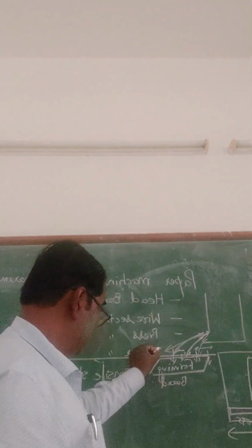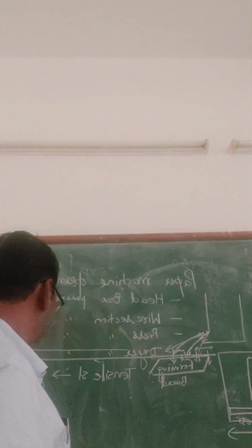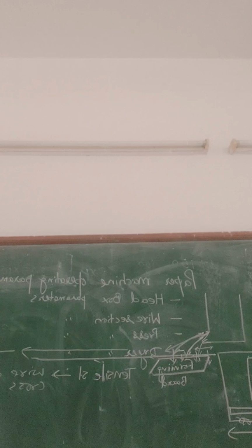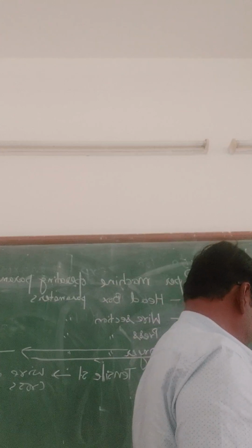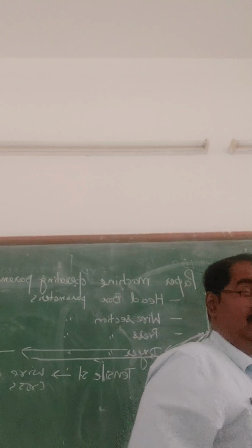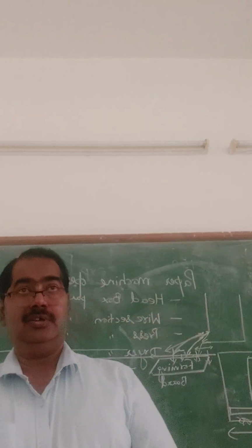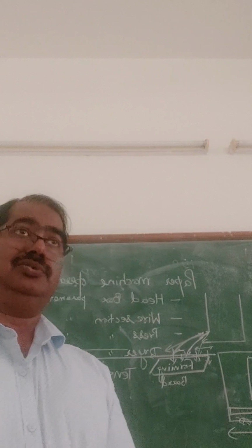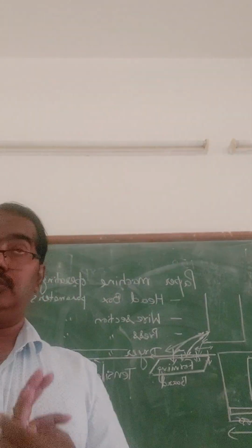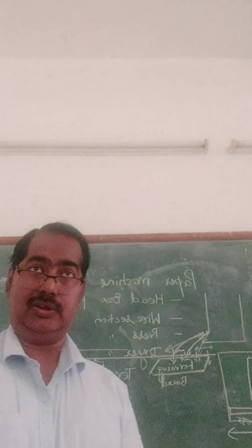Like here, the machine is moving in this direction, then paper will be coming out. So a sample taken in this direction is called machine direction, and across this one at 90 degrees it will be called cross direction. So all the strength properties, like if you are taking the sample for tensile strength, then folding endurance, getting it?